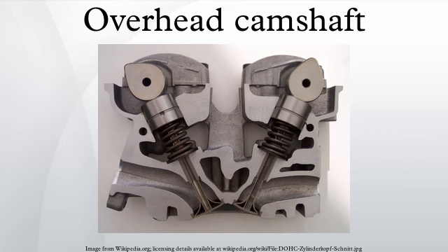Double overhead camshaft. A double overhead camshaft valvetrain layout is characterized by two camshafts located within the cylinder head, one operating the intake valves and one operating the exhaust valves. This design reduces valvetrain inertia more than a SOHC engine, since the rocker arms are reduced in size or eliminated. A DOHC design permits a wider angle between intake and exhaust valves than SOHC engines. This can allow for a less restricted airflow at higher engine speeds.